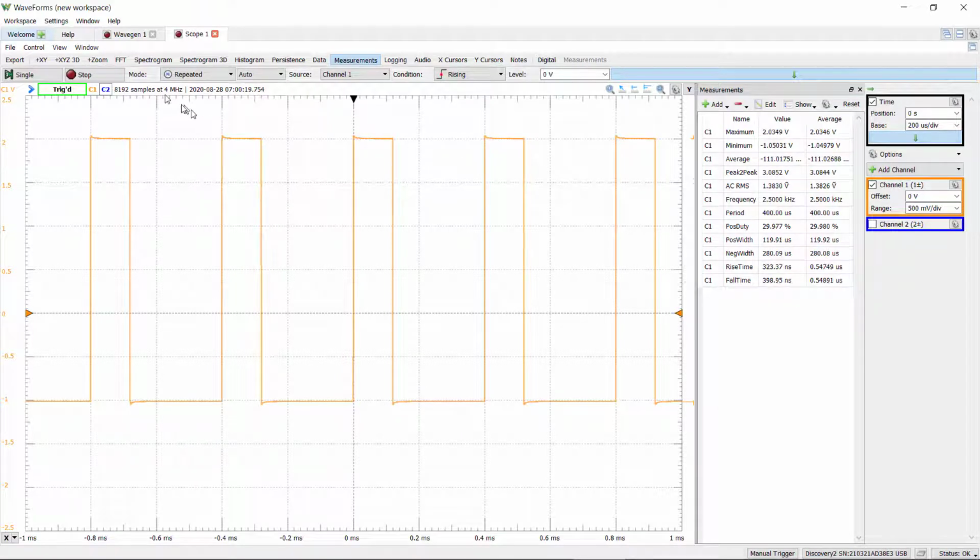Now remember, our sample rate here is 4. We changed the scale. We're at 4 megasamples a second. That means every 250 nanoseconds we're taking a measure. Don't expect to be able to measure a rise time any less than about 200 to 400 nanoseconds. And what have we got here? We got 0.5 microseconds, or 500 nanoseconds. So I could believe this is at the instrument limit.